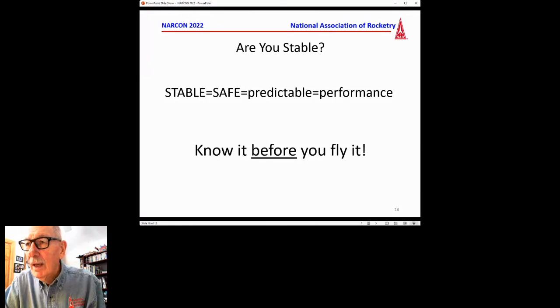If you go tangentially, if your nose cone comes in so that the base of the nose is tangent to the body tube, then it should be a smooth flow. The air pressure stays pretty smooth there. There's no bump.